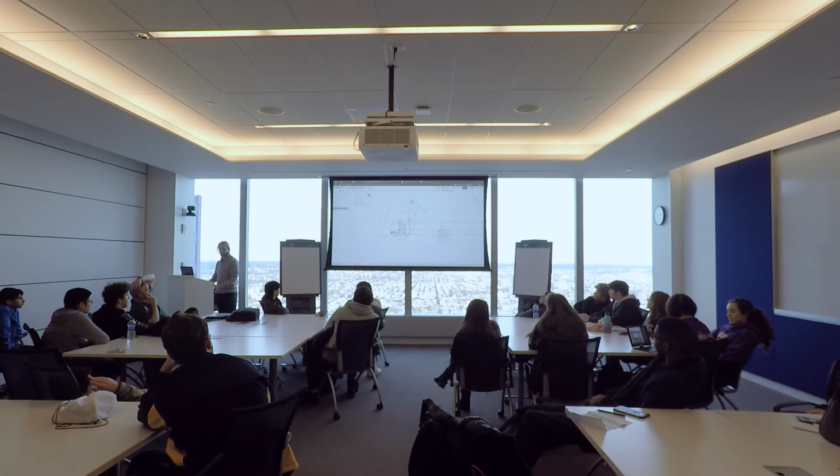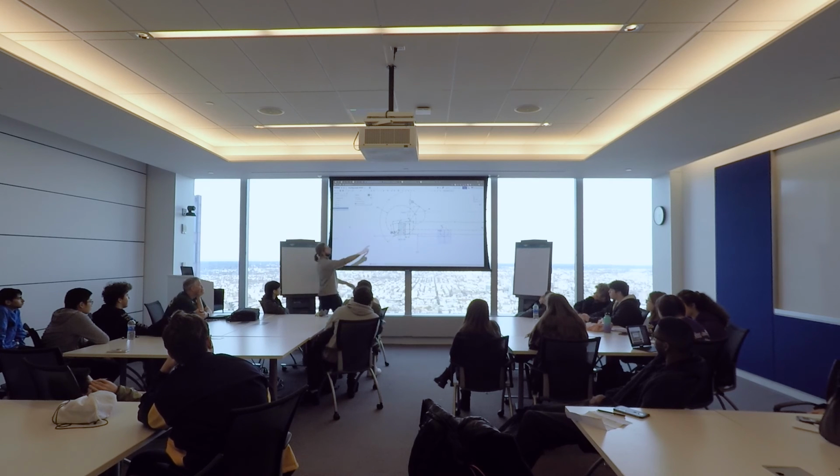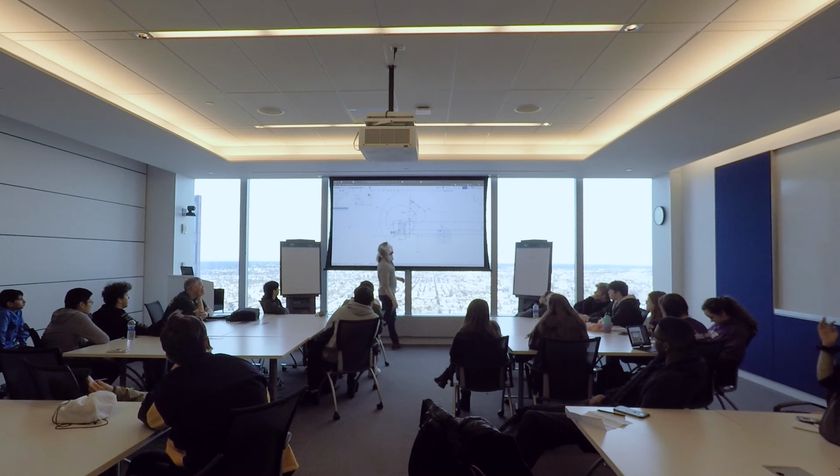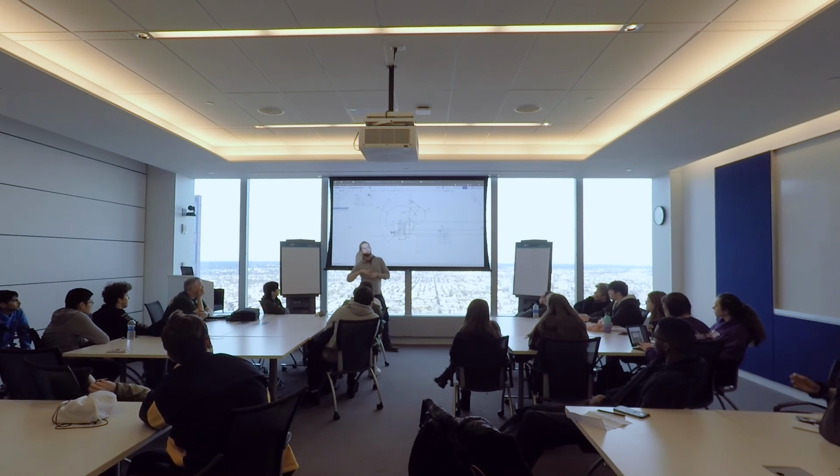Okay. So where these circles intersect is a really important point. And it's actually really cool. It's a very messy sketch here, what you're looking at. But at this point right here and at this point right here are where you would mount a cylinder so that when it extends, it puts the arm from this position to this position.